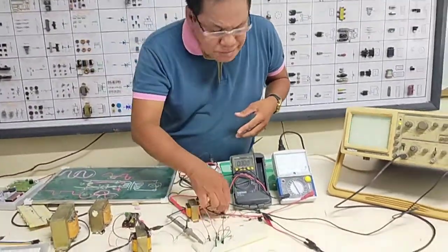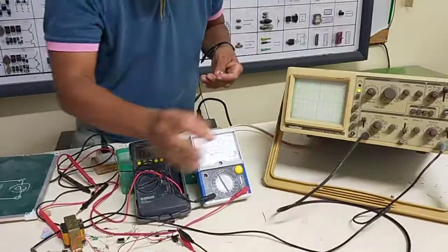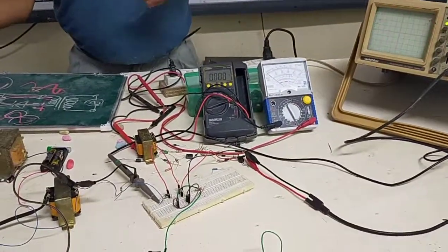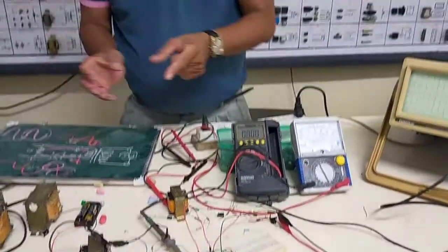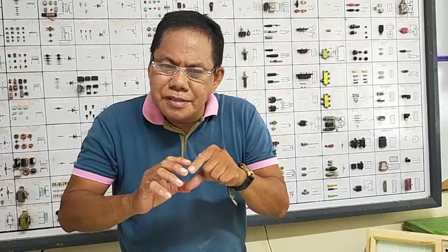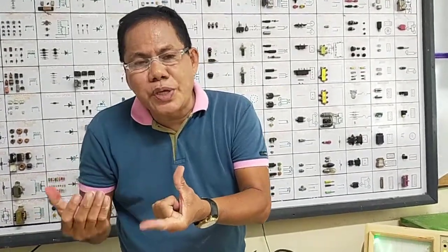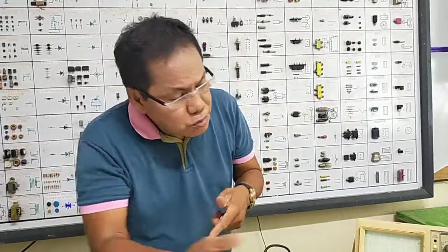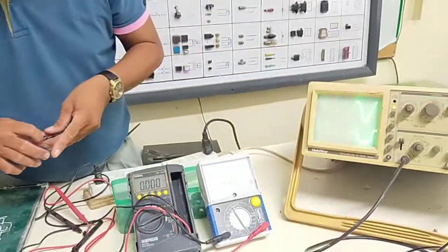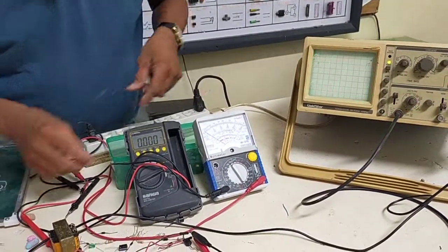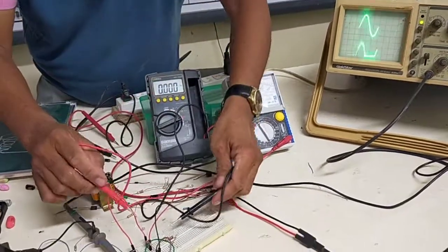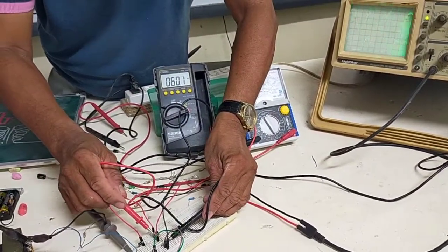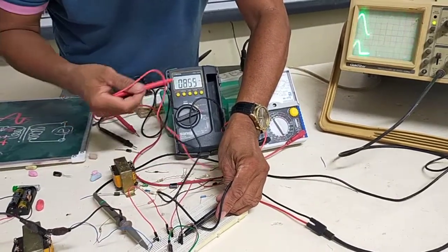Then, we can smooth it out because when you supply that to a certain amplifier or a unit, to your cellular phone, to your amplifier, to your radio receiver, for example, it may cause distortion, hum sound. The music is accompanied with hum or distortion. So, because of this variation, there is still frequency at the output. We can measure the frequency at the output of this diode, that there is still 60 Hz. This is not the output line. The frequency here is 60 Hz.